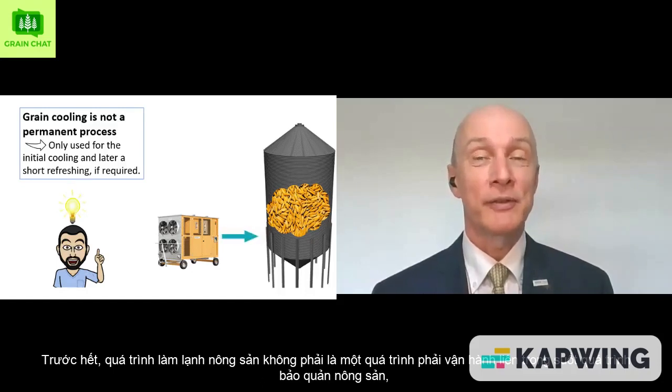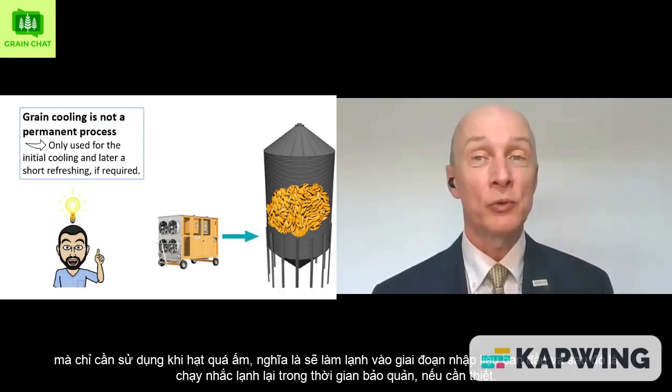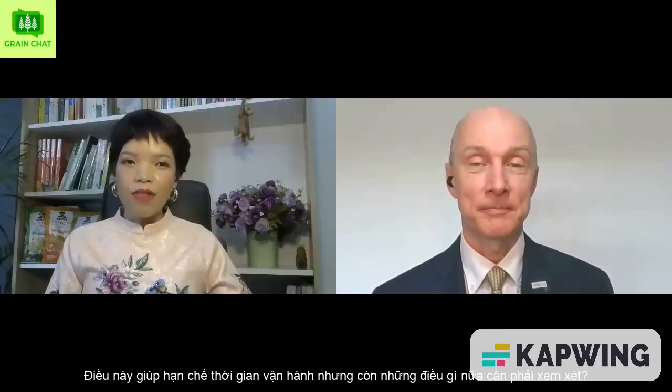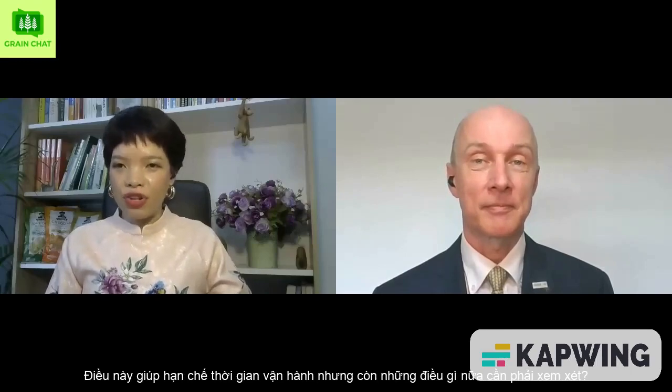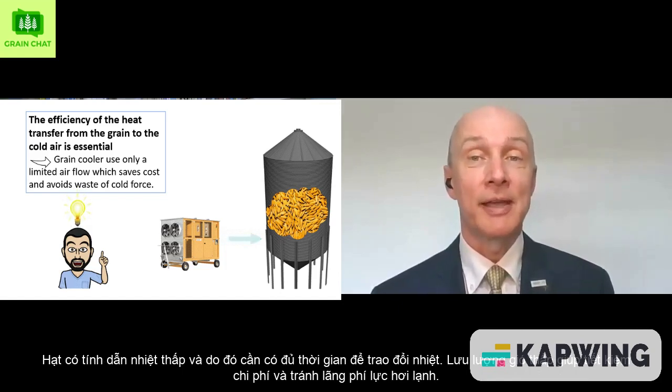First of all, grain cooling is not a permanent process, which is operated throughout the storage of grain, but only used when the grain is too warm, which means for an initial cooling and later a short refreshing if required. That limits the operation time, but what else is to consider? The efficiency of the heat transfer from the grain to the cold air is essential, and that is why grain coolers use only a limited airflow, unlike aeration. Grain has a low heat conductivity, and therefore sufficient time is required for the heat exchange. The low airflow saves cost and avoids waste of cold force.